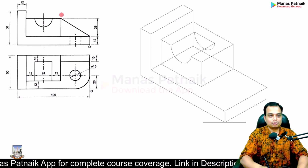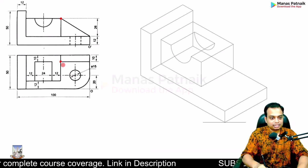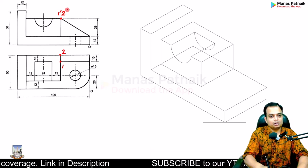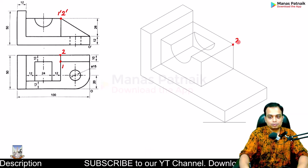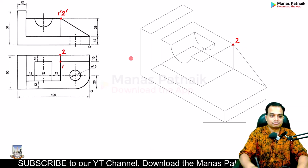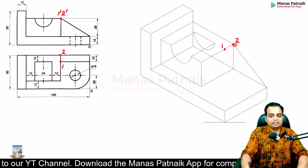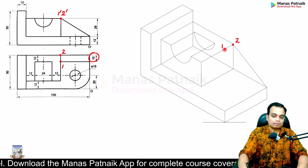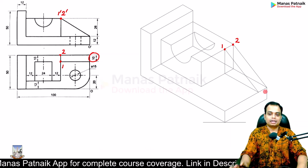Now what? Now there are essentially 2 points over here. One is at the front, one is at the back. In the front view, 1 dash and 2 dash. So the one at the back is this point 2. I mean, this is a sort of a slant. You can make this very easily, and then one can be made over here. The distance between these 2 points is 10 millimeters. So at a distance of 10 millimeters, you can make another point and then again a slant. Come down and to the right hand side. Done. Okay.